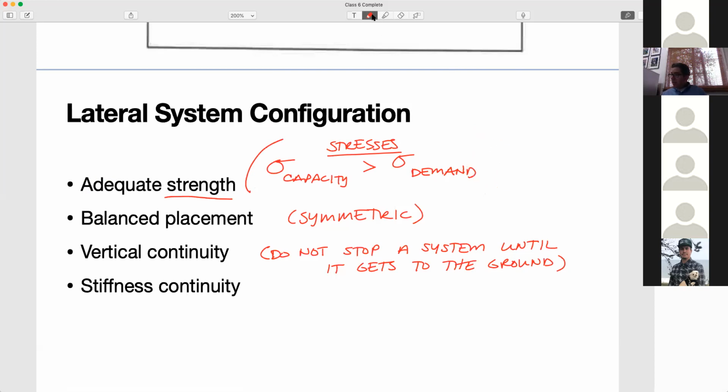And when we get into the handbook, you'll find all this is actually really frustrating. The moment tables in your design handbook are actually what's being incorporated in that. When you have a moment capacity, that would be a strength issue. That's a stress calculation that's masked in there. By choosing that correctly, what we are guaranteeing is that the capacity is greater than the demand.